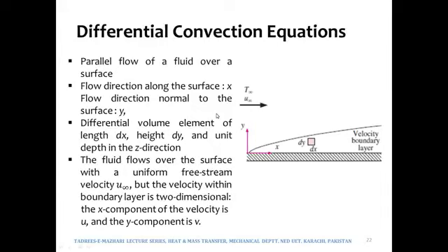Now moving onwards, we are going to start the three famous equations: conservation of mass equation, conservation of momentum equation, and conservation of energy equation. So over here, let's consider that the fluid is flowing over a surface, over a plate, and within this fluid we have this differential element having dimensions dx and dy in x and y respectively.